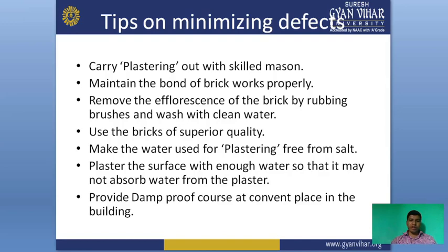Remove the efflorescence from brick by rubbing with brushes and wash with clean water. Before using the brick, we have to wash it with clean water. Use bricks of superior quality, means good quality bricks should be used. Make the water used for plastering free from salt.